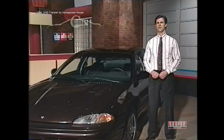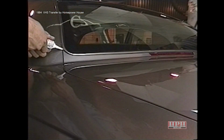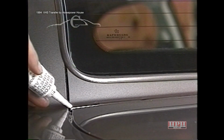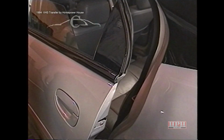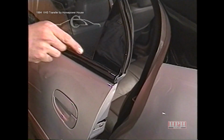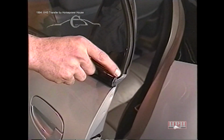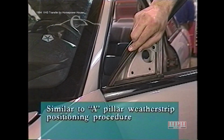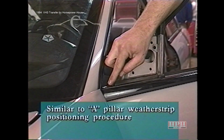To seal any wind noise that may be apparent at the top of the rear seat on New Yorker and LHS models, apply a bead of black silicone RTV below the surface line of the backlight valance panel. When traffic noise is present at the rear door flag on the rear door, check for proper glass run weather strip positioning and adjust as appropriate. If there's an opening, pull the weather strip down into the correct position over the opening.